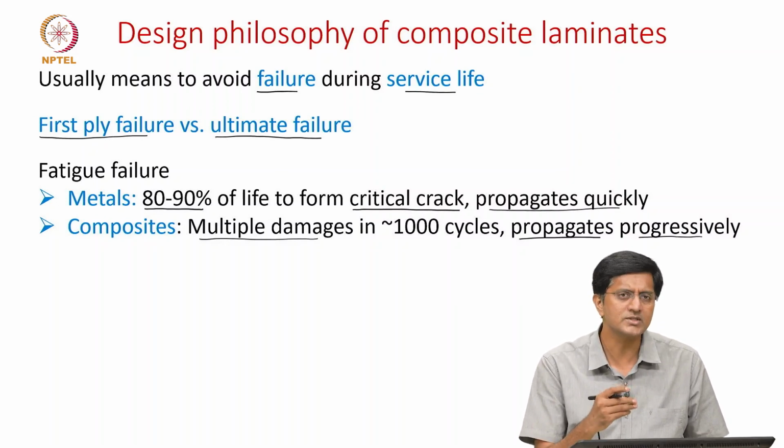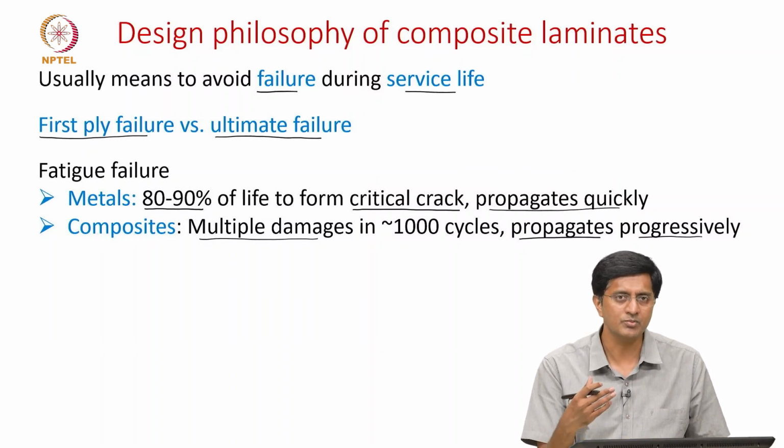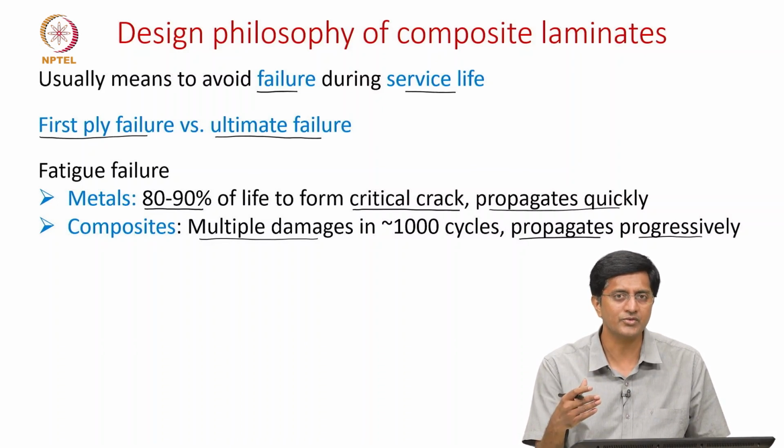What it means is, while we design composites for fatigue failures, we should account for this progressive crack propagation, because the majority of the fatigue life of the component is in the crack growth. So it is better to take care of this while designing these composite laminates.